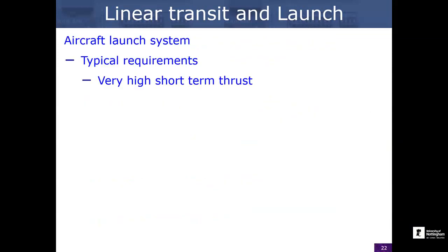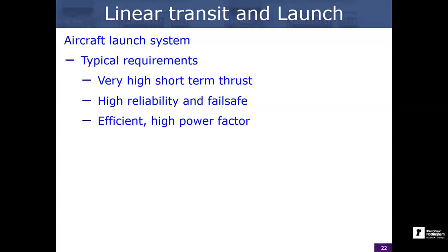But the idea of these is they have a few key requirements. You need a very high short-term thrust. Because you're looking at a very, very high force, you're then looking at focusing all around force production over the short term. You do need them to be highly reliable because they're doing a very specific application. They need to be fail-safe, especially for something like a carrier launch. You can't have a standard of, oh, every 6th plane just gets flung into the sea because the thing fails halfway through. So they need a high level of reliability similar to an aerospace machine.